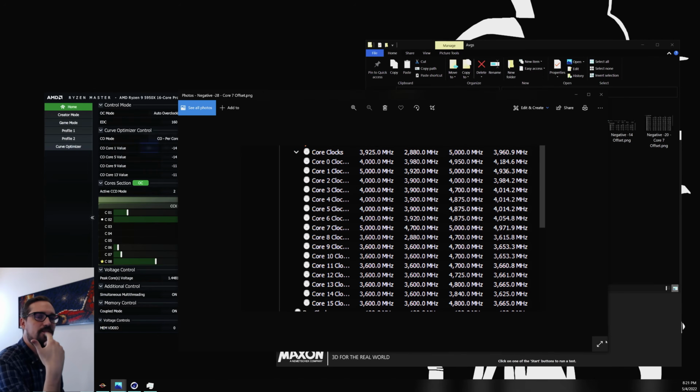The only reason it really fluctuated below 5 gigahertz is because of the change in load, switching between each image that's being rendered in Cinebench. So I actually had a sustained peak boost of 4.971 gigahertz, and pretty consistently it was running at 5 gigahertz at most times. Now this ran stable for 2-3 hours doing normal tasks, playing games, until it didn't. Then it crashed, black screened, rebooted the computer, and I lost the session that I was in and had to start over. Luckily, the game I was playing had an autosave, so I was okay.